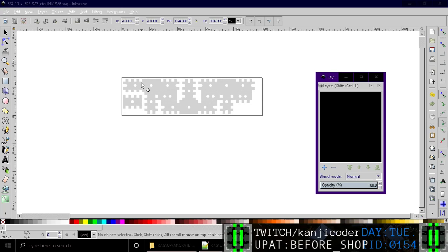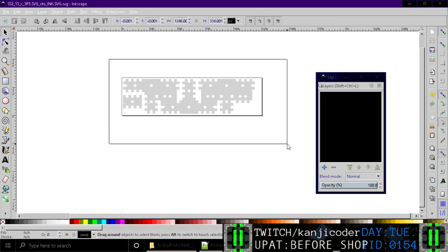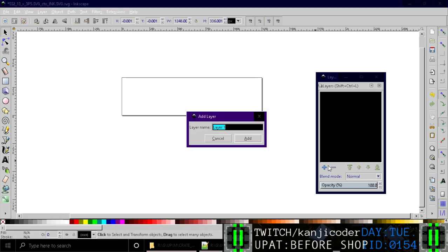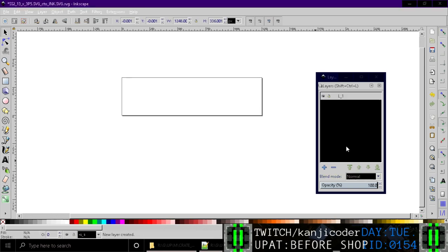The hackish way we're going to do this, to get this to cut, is rather than using very high power and slow speed, it's better to just do high power and multiple fast passes in order to avoid getting huge amounts of kerf. If the laser goes very slow and very hot, it's like a stream of lava coming at your material, and it does not work well. So what you can do is take this, right, and then cut and paste it multiple times.